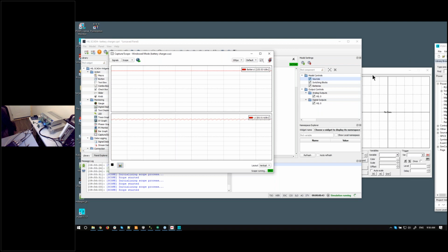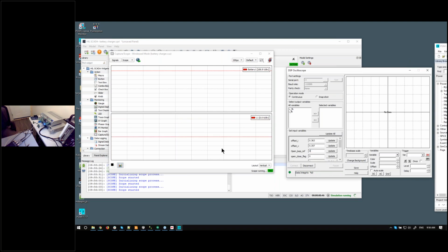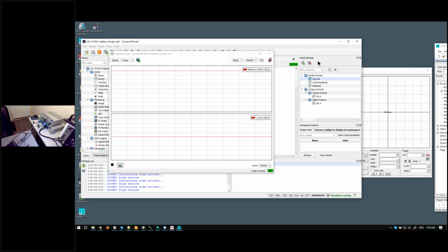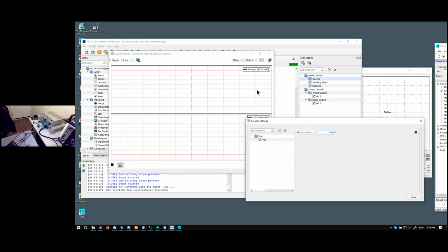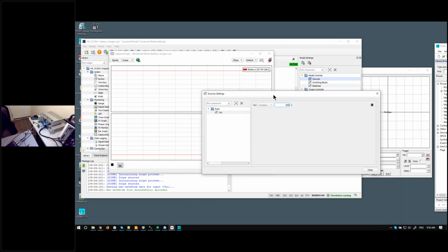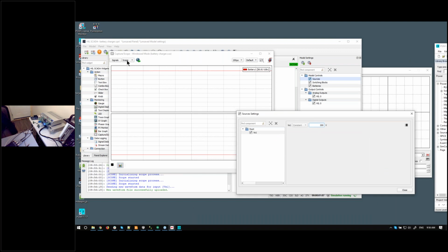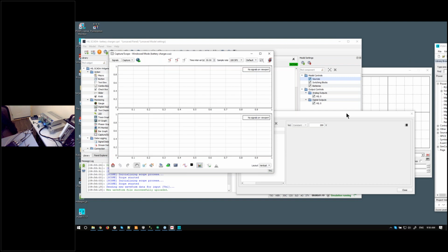Then what I'll do is change the size of the battery. I'm just going to make the battery discharge by dropping the DC bus voltage. So we should see the battery discharge. And then I'll put it back into closed loop. I'll put this to a capture mode, and we should be able to see the battery charge in constant current, and then switch to constant voltage. So we'll go to capture mode now, and I will change this DC bus back up to 700 volts.